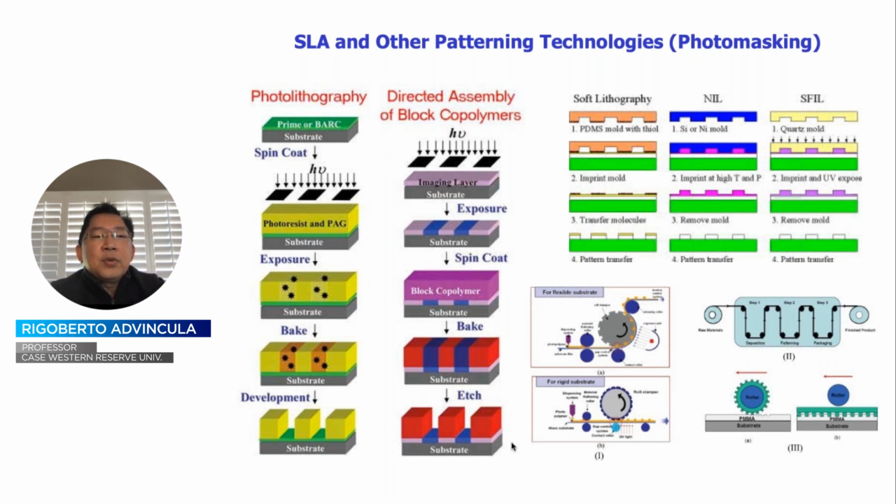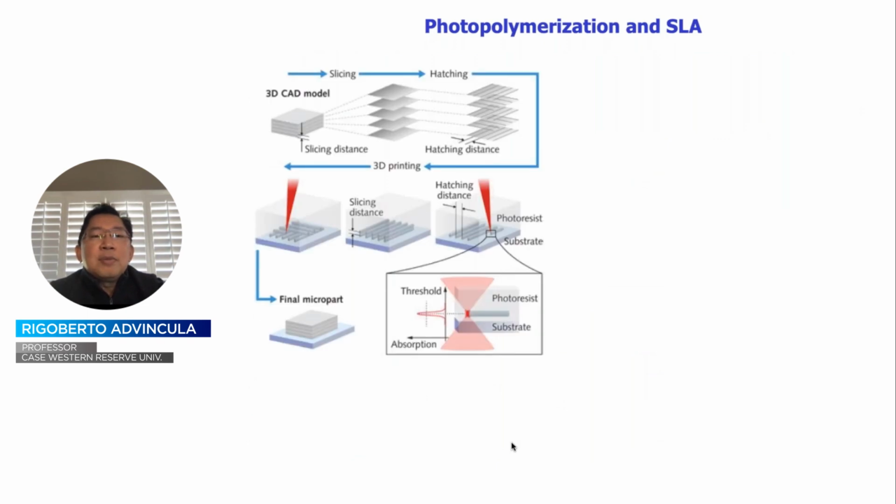So in photolithography, one can assign the chemistry being driven in thin films, and by the use of a mask or photomask, one can limit the exposure to certain regions. And this has been carried out, for example, with patterning, even with directly assembled block copolymers or self-directed type of structures that goes on towards the nanolithography or nanometer scale. In, let's say, soft lithography, nanoimprint lithography, these are alternate methods that use mechanical imprinting, but the same chemistry can actually be used to enhance these other types of non-lithographic processes. Hence, the chemistry is essentially a photopolymerization method.